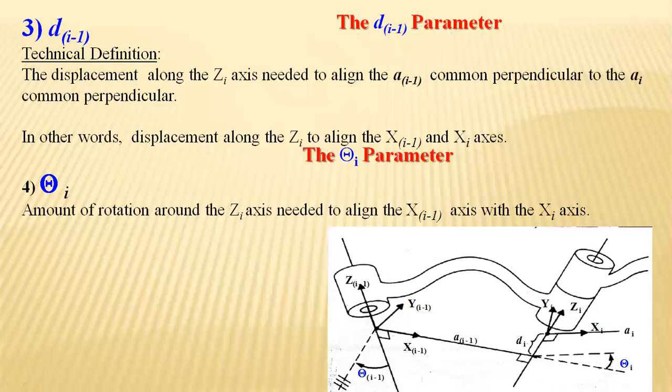And the fourth parameter needs to be identified here. It is the phi representation. Phi is nothing but the orientation. This is the phi orientation. So how much is this orientation towards the clockwise, about the fixed axis of rotation towards its z_i link, and x_i minus 1 link with respect to the x_i axis.